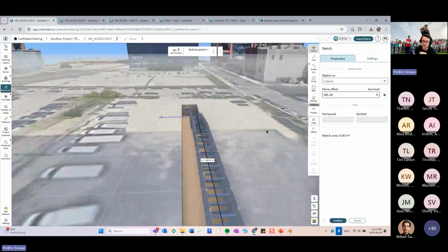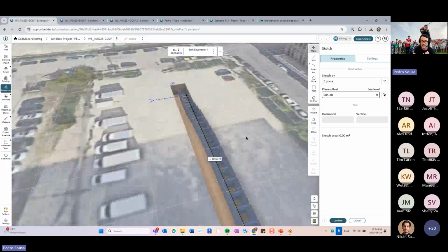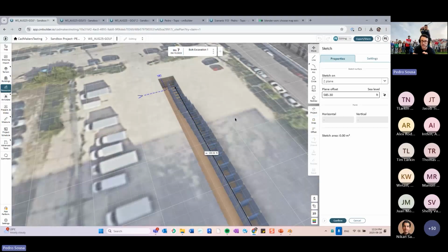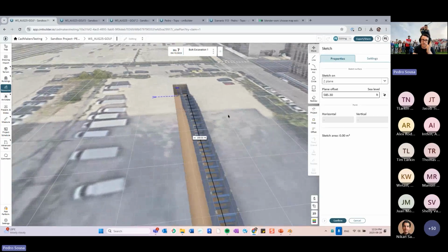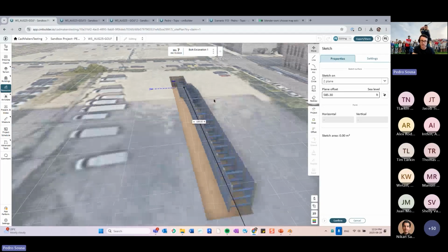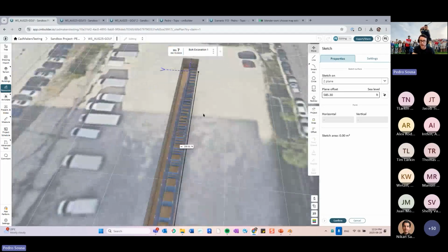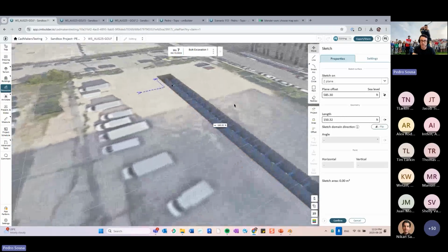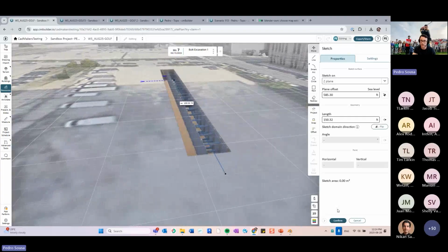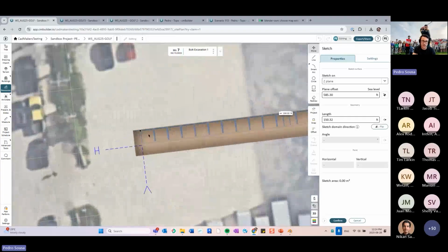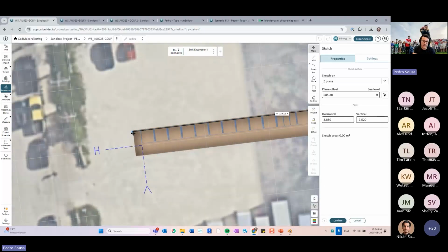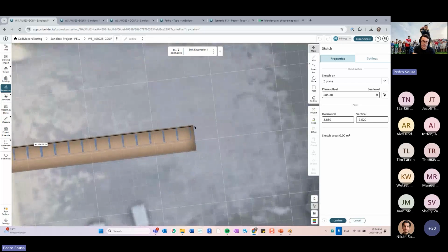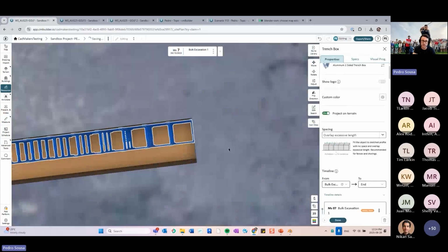And it's important, whenever you're snapping lines to the face of an excavation, to not snap exactly, but either inside or outside, because otherwise the software doesn't know what is supposed to be up and down. So you can move this inwards a little bit, and then it will adjust to be only on the ground, right? So from here, we can go in and then extend these lines to adjust this a little bit further and control what is going to be the location of those boxes.